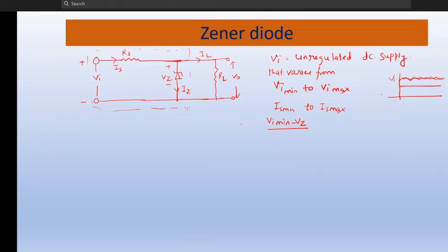Okay, if we say that Rs also varies, because there can be an Rs minimum also, because this is a design problem, R max minus R min. Why will it be Rs max, why Rs min? We need the minimum, sir, that's why minimum, right? So maximum resistance with Vi max minus Vz, because this is constant, Rs min, R minimum. Right? See, this is a design problem, right?